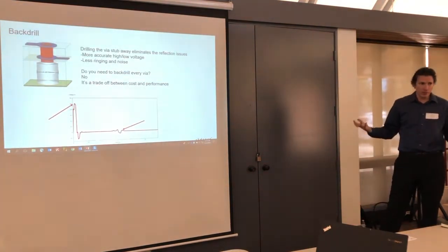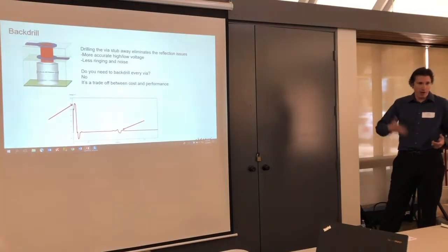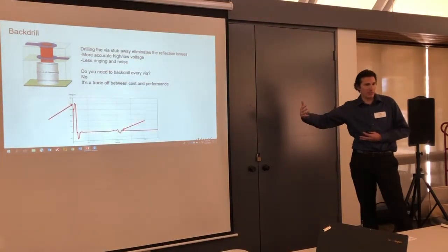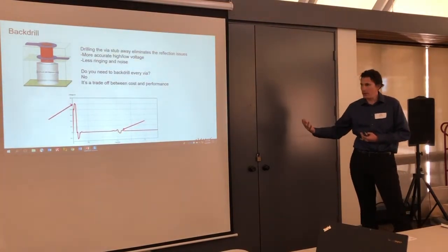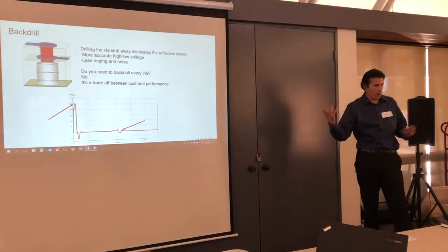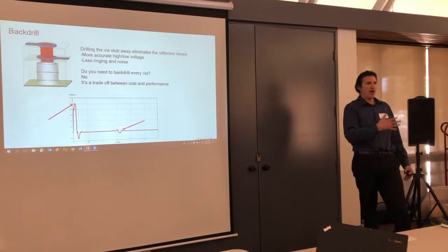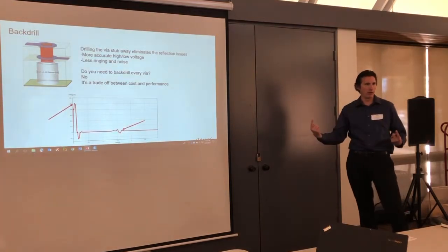You don't necessarily need to back drill your vias in your design. It's a factor of how quickly those things are switching. Is that noise going to compound itself to affect what the receiver ultimately needs to interpret as a 1 or a 0? Most software out there has back drilling abilities. It can say, what happens if I back drill everything? How many back drill hits do I have on my board?